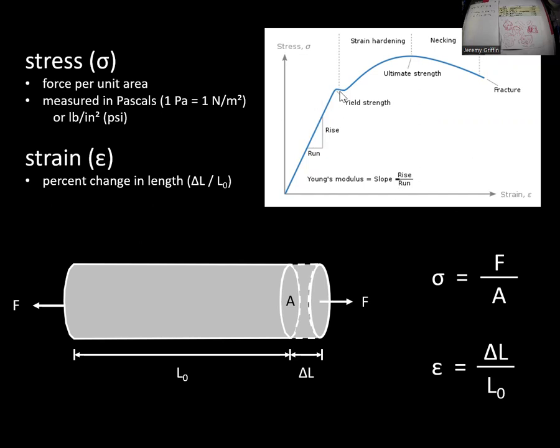Okay? Now, where that elastic zone runs out is the yield point. You guys see this yield point? Now, anything in the elastic zone, you put on the stress, it'll strain a little bit. You take off the stress, it goes back to its original shape. Right? And you can do that a long time until it eventually tires out. And so there's a term for that. It's slipping my mind, when it eventually wears out though.